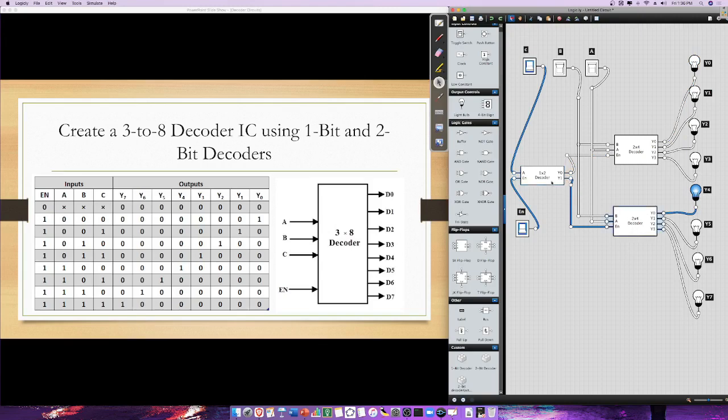Okay, because of this switch. This IC is now selected because the output of Y1 enables this IC. And since this IC has an input of 0, 0, the output will be at line Y0. So that's the explanation. Okay.